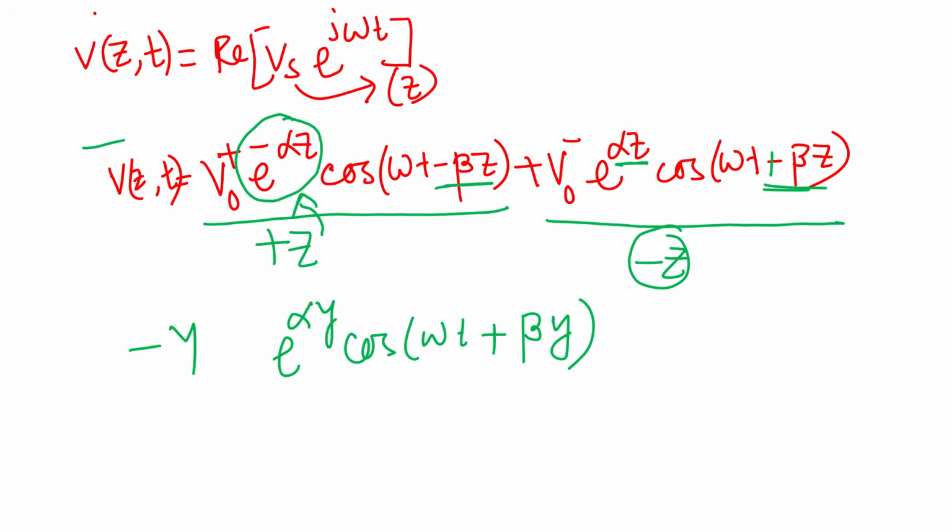So it will depend on what direction of wave we are assuming. Here we assumed our transmission line is aligned along the z axis, so the direction of wave propagation is also considered in terms of z coordinates. If we assume that our transmission line is aligned along the y axis, then this z term will also change accordingly. So this is the expression of instantaneous voltage.